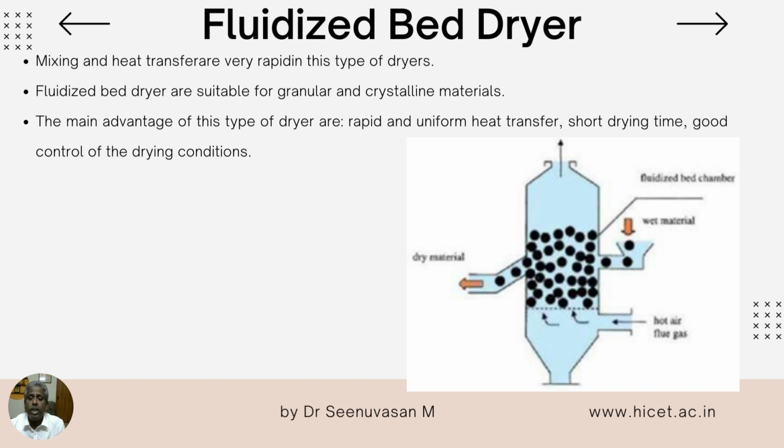Again, I am repeating that the rectangular fluidized bed dryer is a very sophisticated dryer. In this case, separate fluidized compartments are provided through which the solids move in sequence from inlet to outlet. These are known as plug flow dryers. This is very important: fluidized bed dryers are otherwise called plug flow dryers.